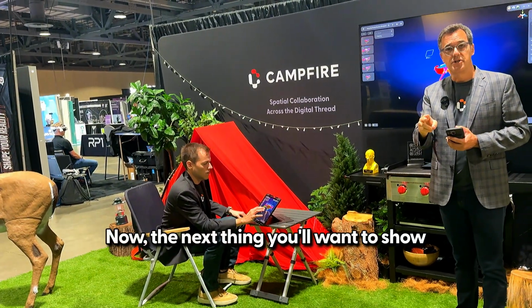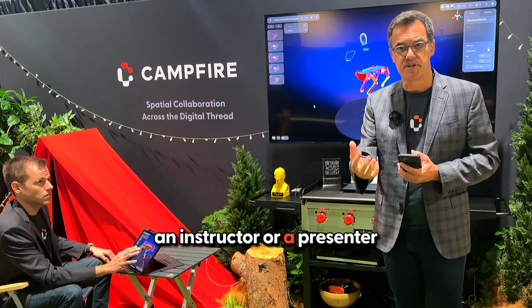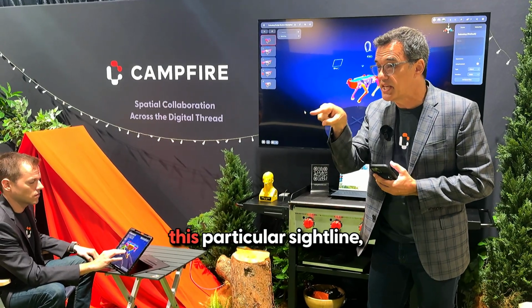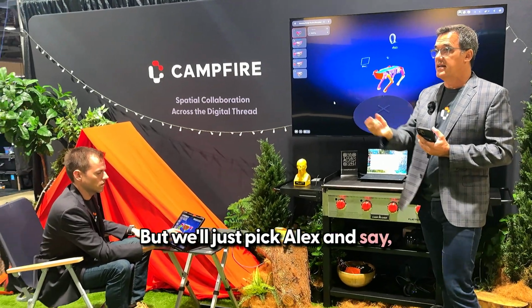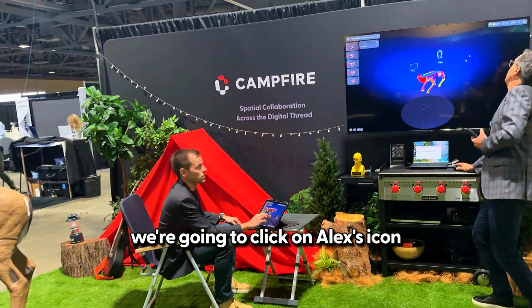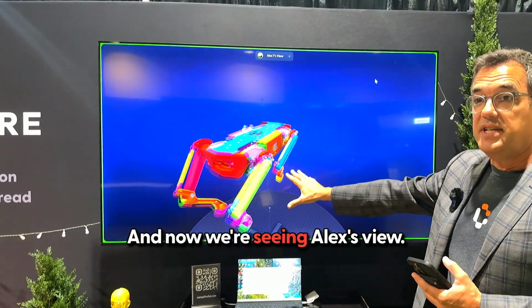Now, the next thing you'll want to show is how you can follow a presenter. So there are often times in presentations where you might have an instructor or a presenter that needs other people to see exactly what they're seeing. And there's a lot of cases for this, but maybe it's like, hey, I want to look at this particular sight line and I need everybody to see what that looks like. Very easy to do in Campfire, as you know, but we'll just pick Alex and say, let's imagine Alex has asked us to follow him and look at what he's looking at. We're just going to come over here, we're going to click on Alex's icon, and we're going to say follow. And now we're seeing Alex's view.